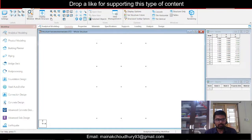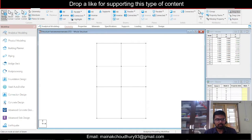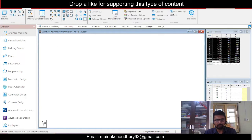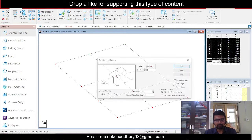After that, go to geometry and click on add beams, and we'll join the beams like this. Once the beams are joined, this is the plinth level, so we'll go to select and choose node cursor. Node cursor will select all the nodes here, and from the proper view we can go to the isometric view, and we'll use the translation repeat option to extrude back to the foundation level.